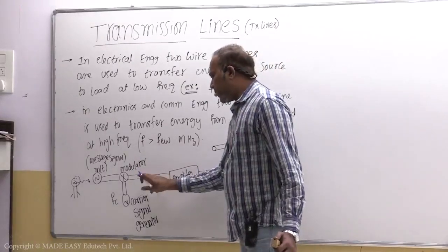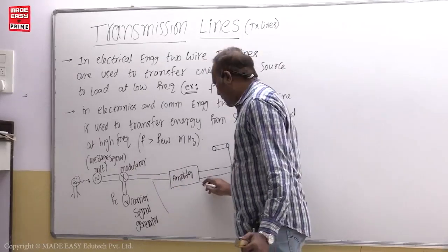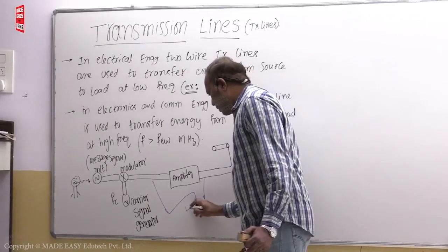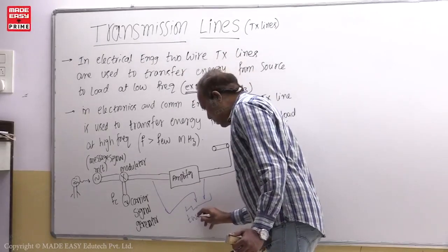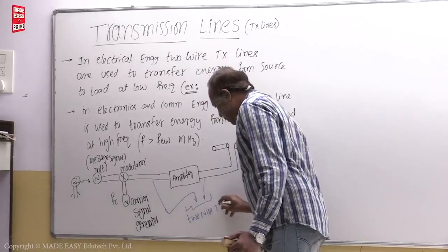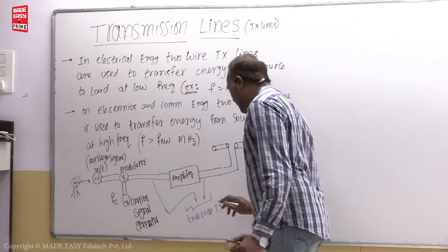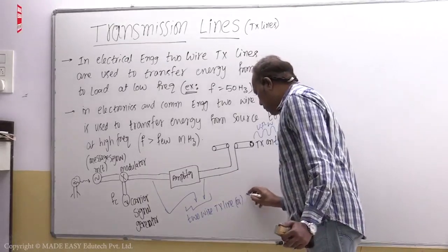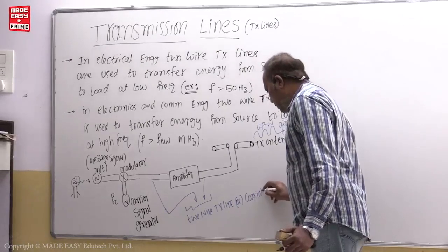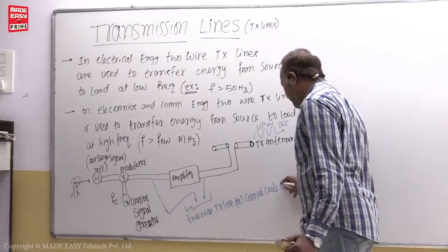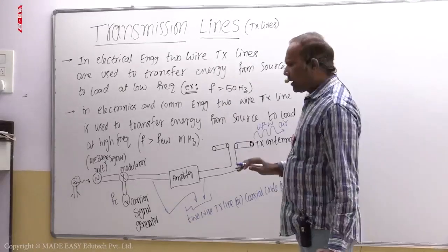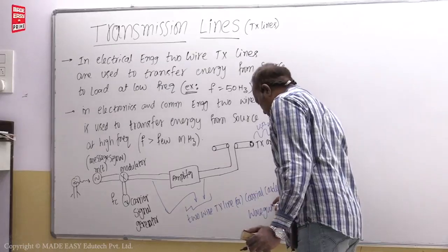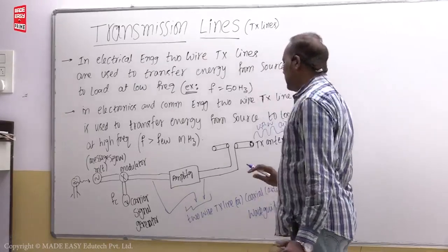If it is transmitted into the air medium, you see here, this is a high frequency signal, FM signal here, and these two are actually maybe a two-wire transmission line if frequency is less, or otherwise coaxial cable for a little higher frequency. Further high frequency, then it is waveguide.